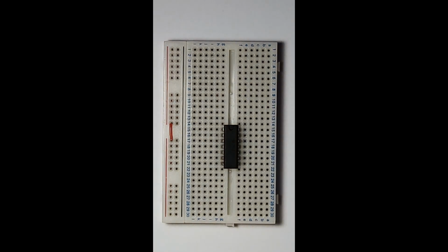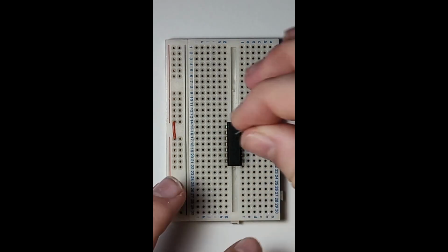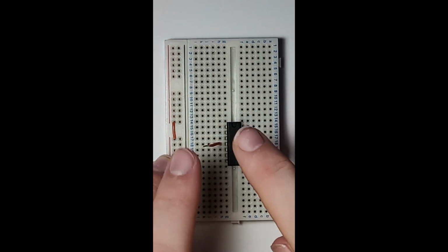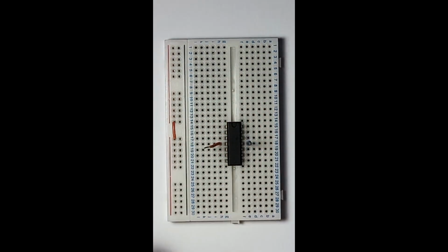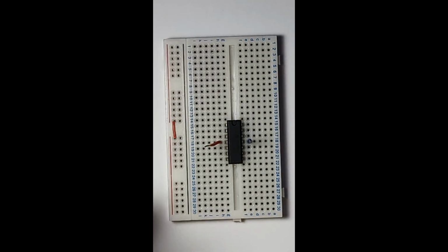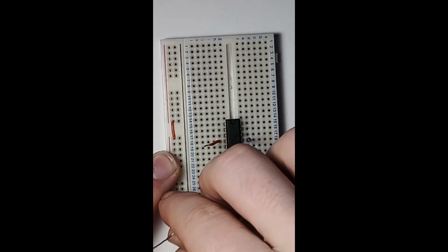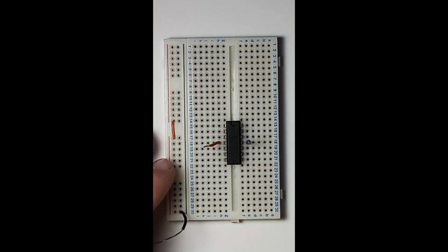To build a circuit, we start off with our quad op amp, the TL084CN. So first we need to power it. So I'm going to add this blue cable and this orange cable, which will be positive 15 and then negative 15 volts. We also want to add a grounding cable so we can connect our alligator clips to the circuit.